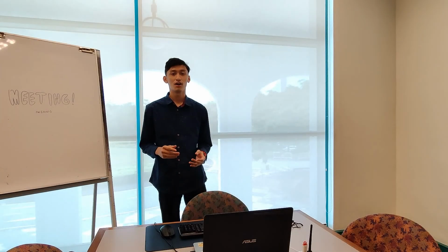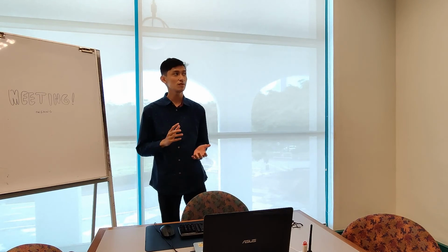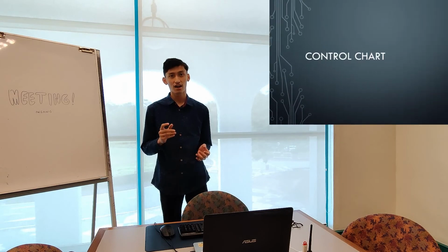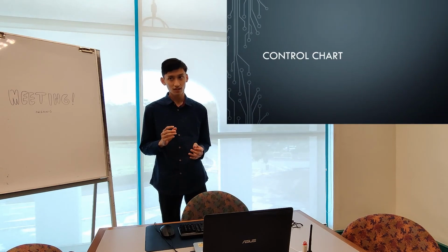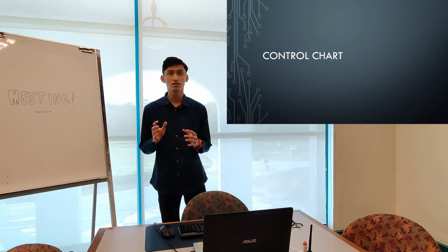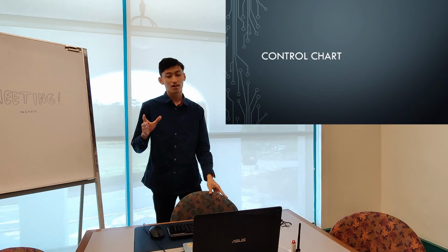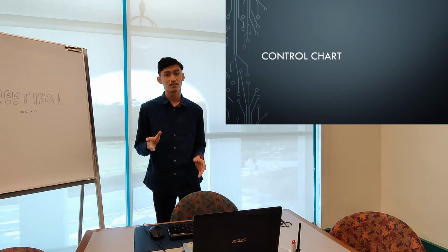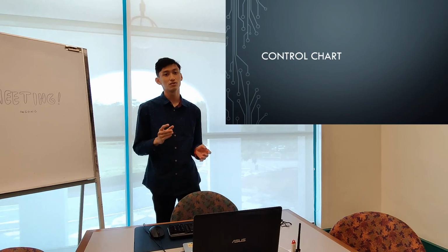Of course. So I will add on our production process performance. Basically, we can use the X bar and R control chart to analyze and evaluate our data, to see whether our production process performance is in control or out of control. The X bar and R charts are a pair of charts that we use to identify and monitor process variation over time.